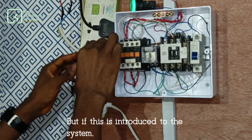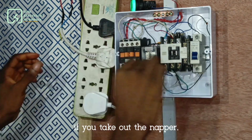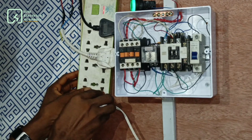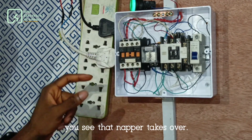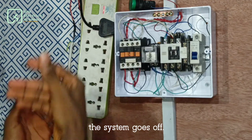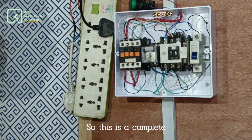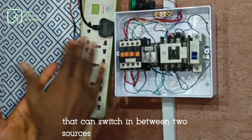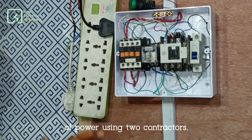But if this is introduced to the system, if you take out the NEPA, or even if you plug it out from here, you see that NEPA takes over. And when you now take over the gen, the system goes off. So this is a complete automatic changeover that can switch in between two sources of power using two contactors, one relay, and a breaker.